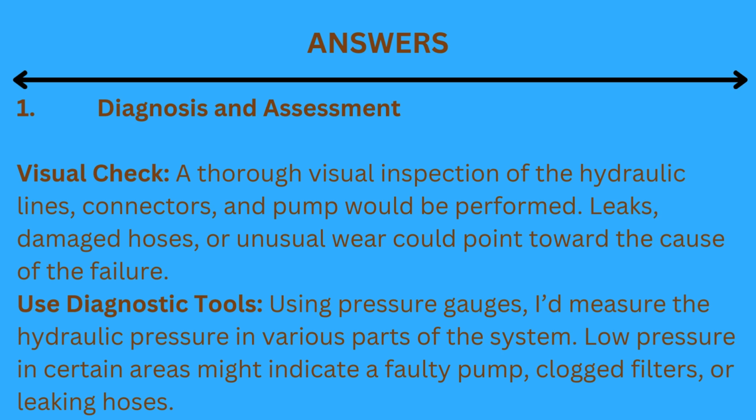Use diagnostic tools. Using pressure gauges, I'd measure the hydraulic pressure in various parts of the system. Low pressure in certain areas might indicate a faulty pump, clogged filters, or leaking hoses.